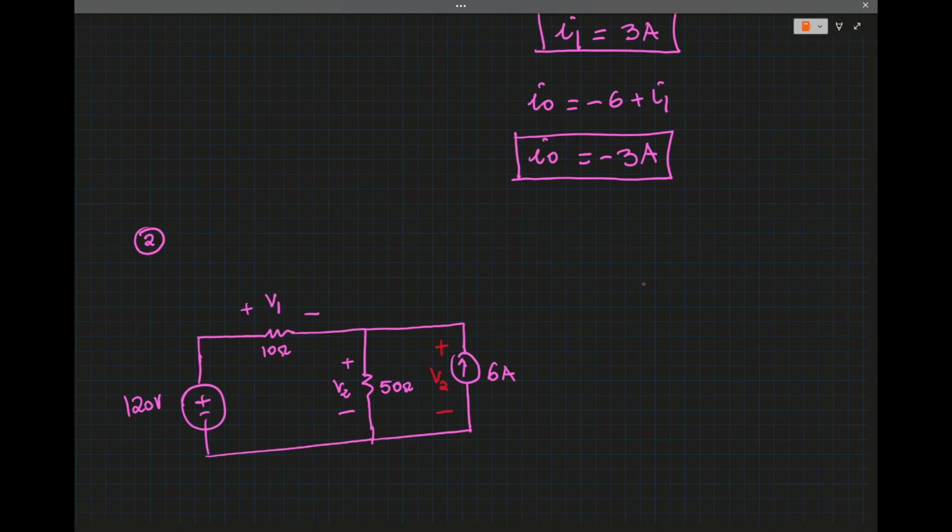So when we have elements that are connected like this, so this is 1 and this is 2, right? They share this common node. So the voltage here, V, will be the same voltage here, V. We say that these two are in parallel. Okay.